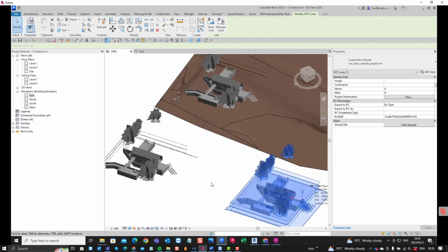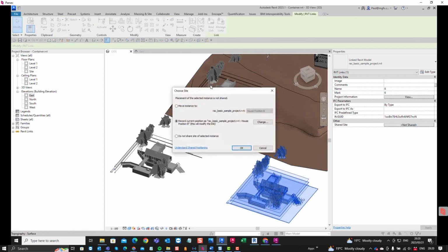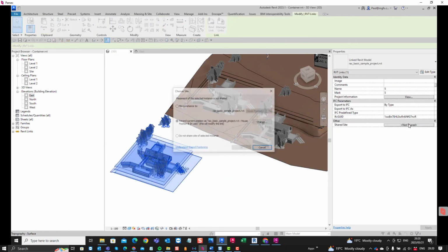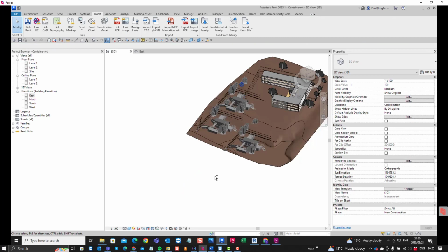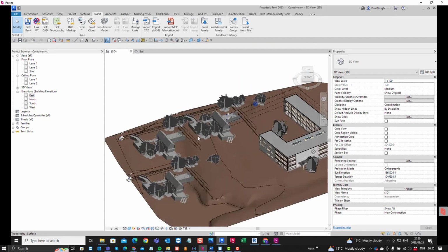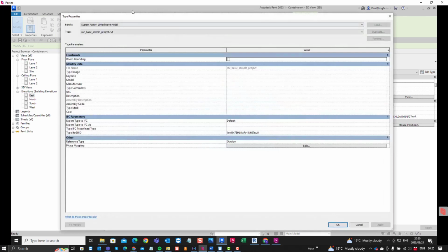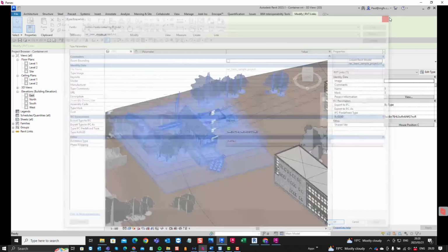If you copied that link, say twice, then for each one of those, you can position them. There's B, and there is C. Right, so it's the same instance, but they've got different shared coordinates. If you have a look at the instance properties, that's your coordinates, and in your site properties you'll see that it's just the RAC base example project.